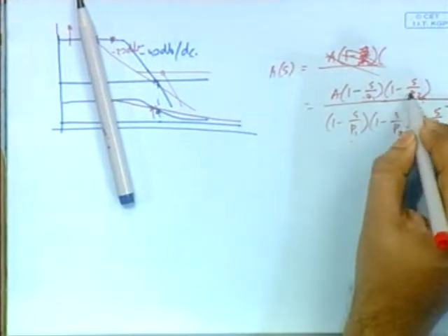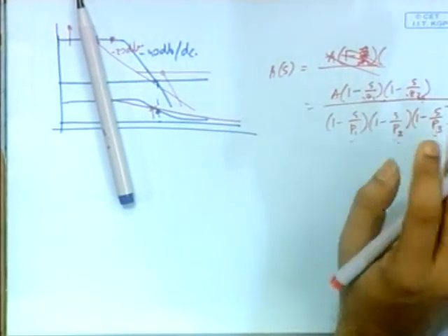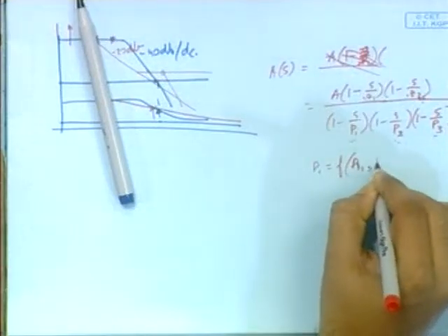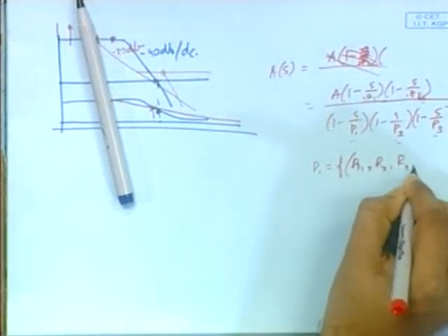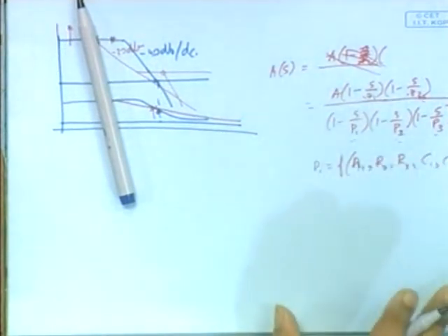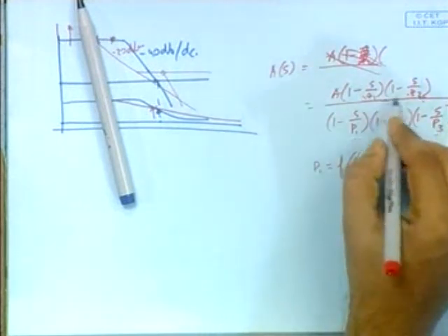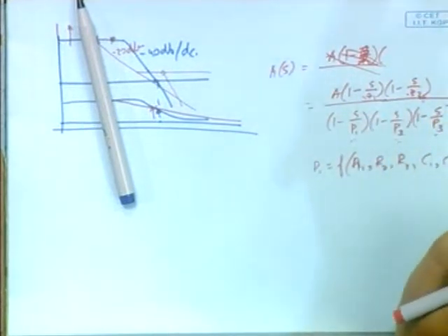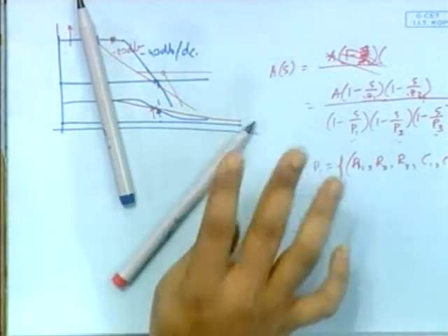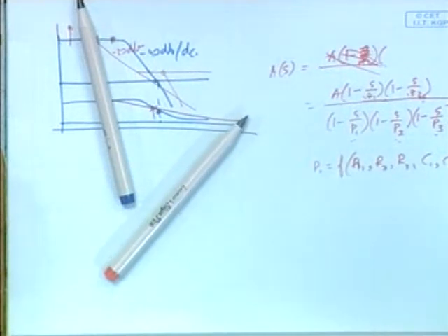And then once you have these poles and zeros, you have your equations in terms of R1, R2, R3. Like say there will be P1 as a function of say R1. There will be 3 R's in the circuit, R3 and maybe some C, something like this. Similarly, all these will have standard expressions, and you put in the values of Z1, Z2, P1, P2, P3 arrived from your control system analysis and get the proper R2, R1, and then you have your error amplifier ready. So that's the way we get our controller.